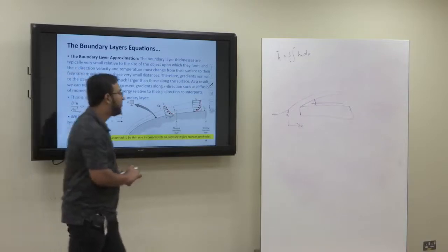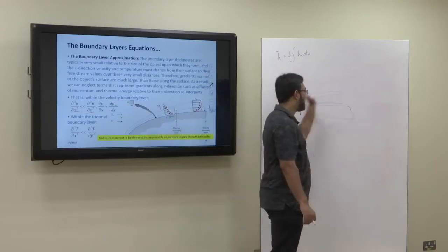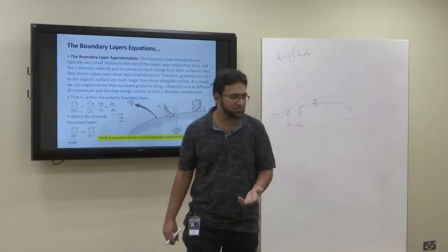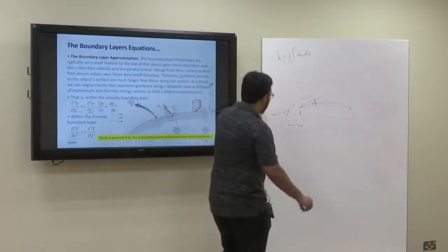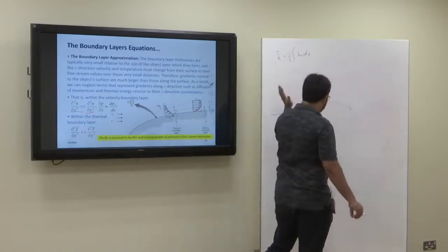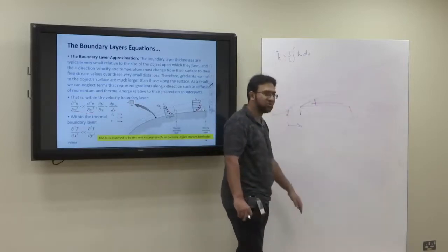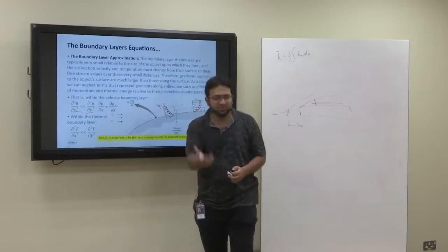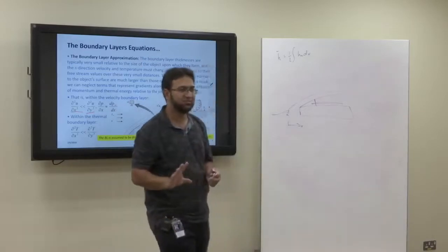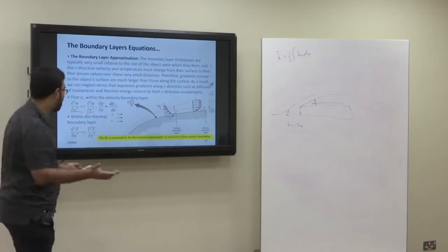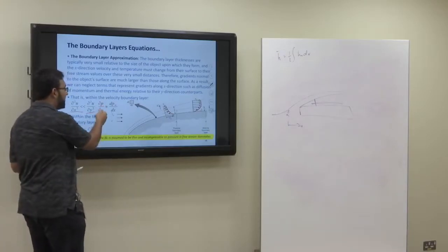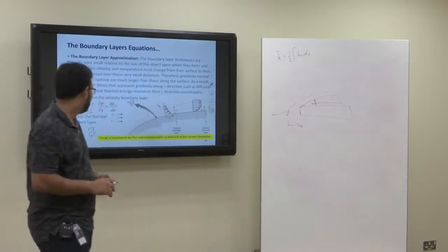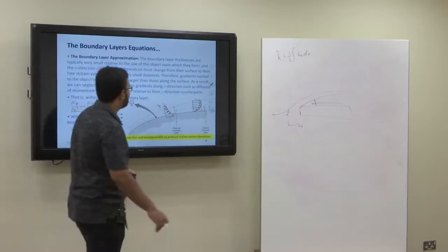Then the flow is flowing from right to left, okay, from this end to that end. So flow occurs because of the pressure difference. That means we have high pressure here, low pressure here, and the flow is flowing in this direction. There is no flow in the up or down direction. So that means there is no pressure difference in the y direction. Although there will be a slight pressure difference in the y direction, that's negligible. So that's another approximation. Okay, so basically ∂p/∂x becomes dp/dx because it's only varying in the x direction. And similarly, we have these approximations for the temperature.